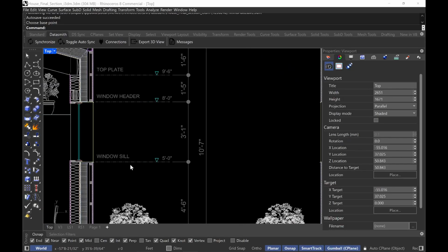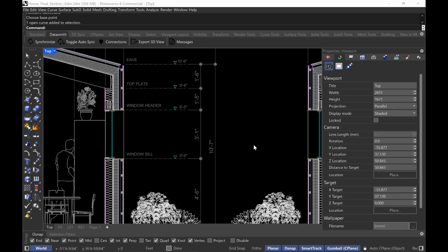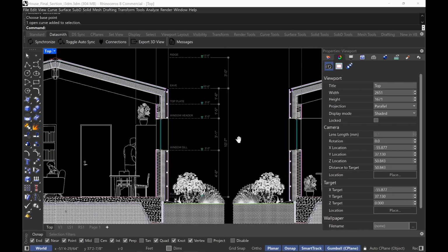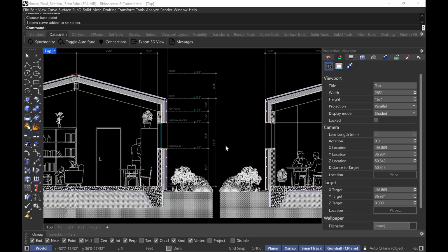So for example, here I changed the line type scale. So if I go here, its line type scale is 24. You see? I can readjust it some more in Illustrator, but I did it on here anyway. Okay? So again, just remember that once you take it up to this point in Rhino, make sure everything's at the correct scale, especially your hatches. All right?